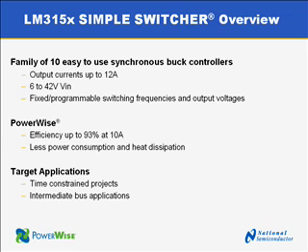That means you have less power consumption and less heat on your board. The applications that we are looking for are projects where time is an issue and applications where you have to supply an intermediate bus, like from 24 volts to a 5 volt rail.